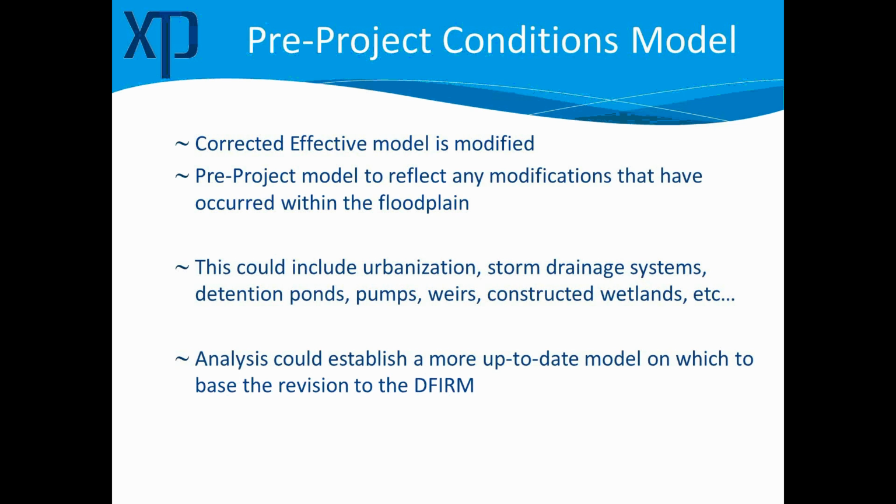And then you have 5 or 6 other watersheds, and then how does it combine those hydrographs? And then we would do the combine, and then in times past we would do a routing run. So we would go to HEC-RAS or HEC2 and then route those, get some storage values out, and put those back into the hydrology model and do quote-unquote storage routing.